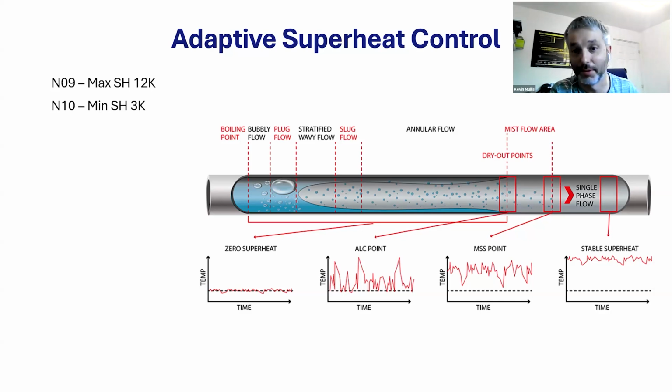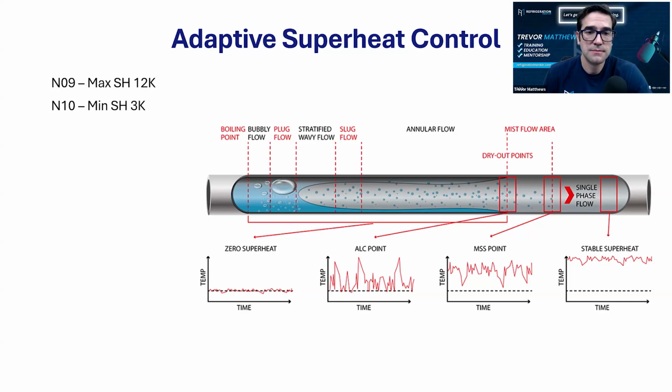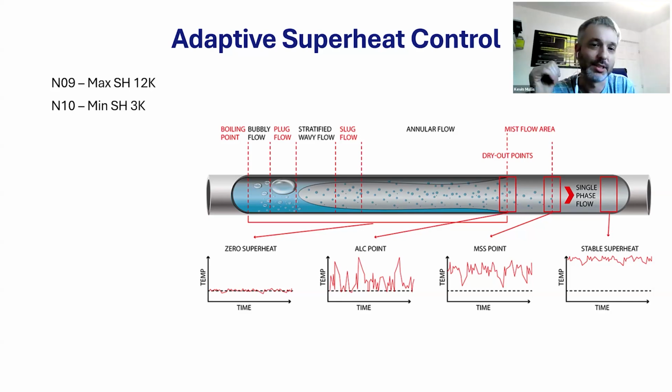It does tell you here, like I said, I don't think, unfortunately, we've got time to go through it all today, but you will see its target superheat move up and down depending on what it can do to stabilize the coil. So you need to give it a range to work in, but don't make the limits crazy because it won't work properly. We tended to set the maximum to 8. And let the minimum start. I don't think you can set the minimum much lower than 3 and still have it work. You need, especially with DX stuff, a little bit of room because your sensors take time to react. If you set that really, really low, by the time your sensors worked out that your pipe's got too cold, you're already flooding back.